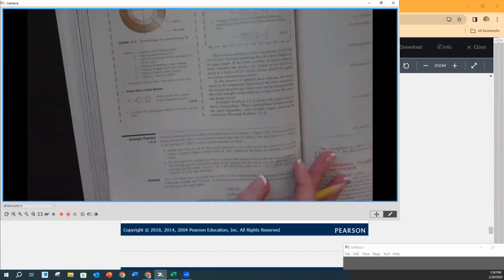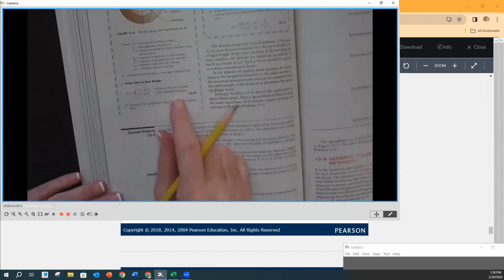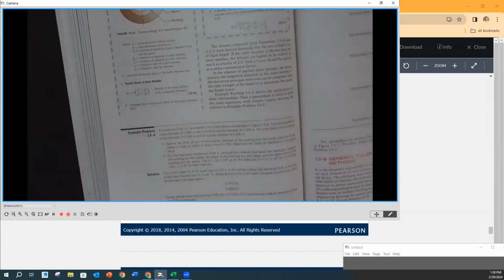Okay. So that's what the little V's are, Poisson's ratio. It'll be given to you when you need it in the problems. If you need to put it in, if it's not given, just use 0.27. That's a very standard number because a lot of metal materials react very similarly in those two directions. So when in doubt, use 0.27, and I have that on the chart as well, or on the Excel spreadsheet. And then that's going to compute the pressure.